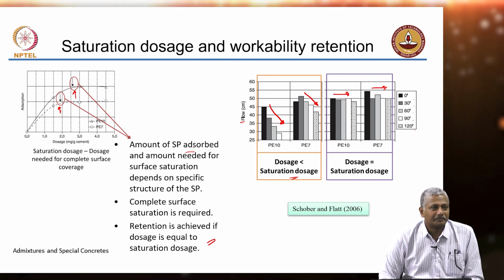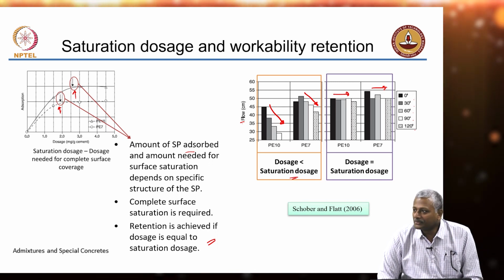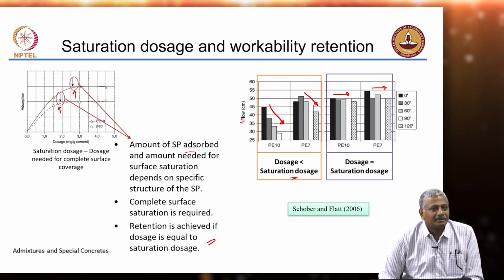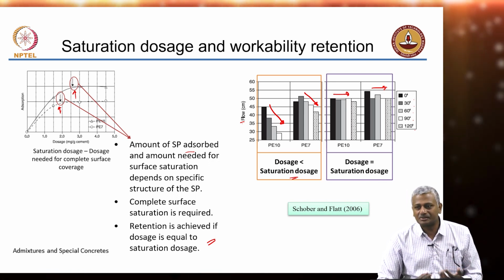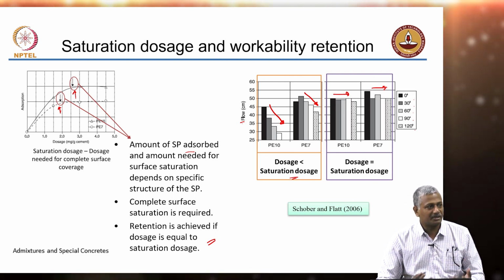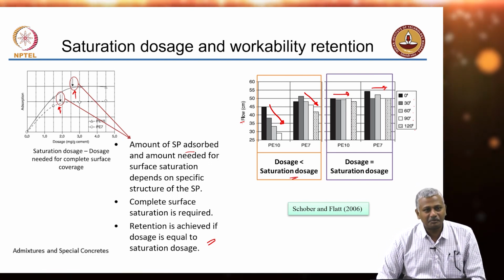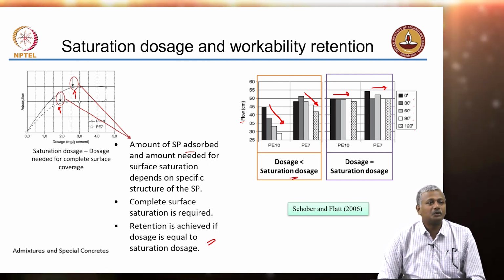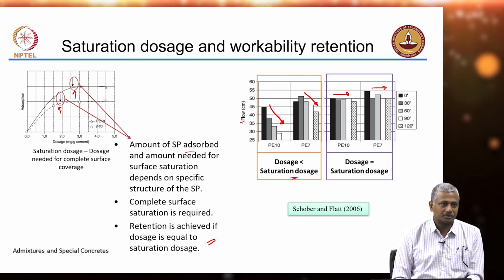Exactly. The site is not ready to take the concrete. The truck is simply standing on site. What happens during this time? The slow rotation continues, but the concrete is losing its freshness, it is losing its workability. So, you may have some extra addition of admixture on the site. Now, when you do this, you are obviously pushing your admixture content much above your saturation dosage.